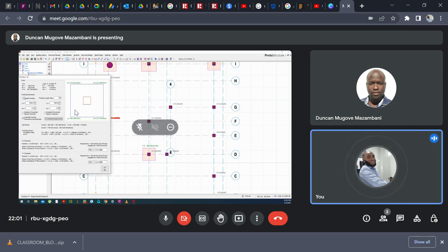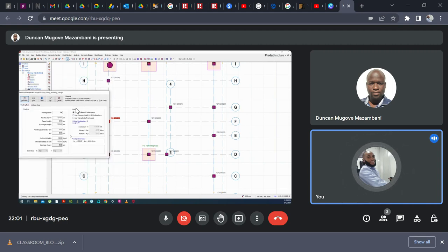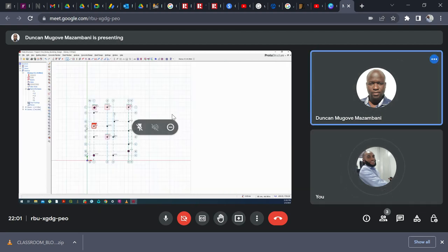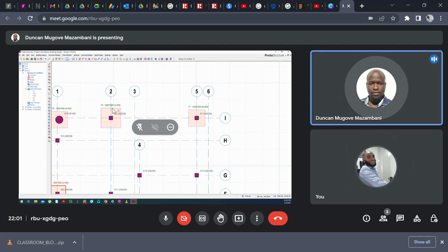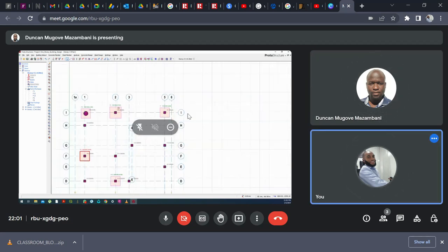Okay, the same thing; this is what we naturally got. But if you do a larger building, that's when you'll be seeing different depths and different sizes of footing. Say okay. The only bigger one that we got is this one, 1.2 by 1.2. That's the highest there.